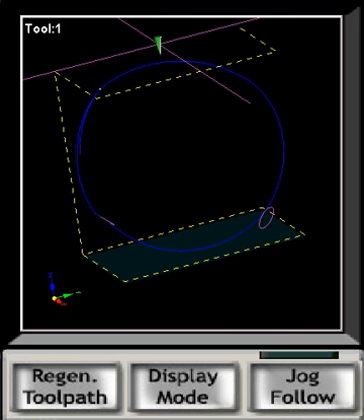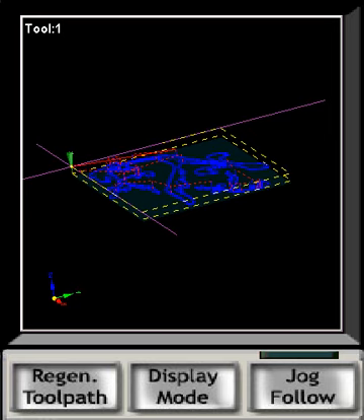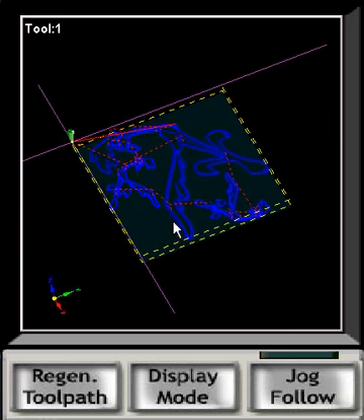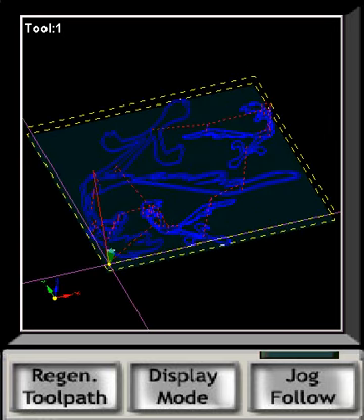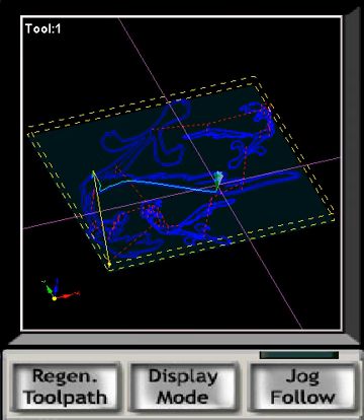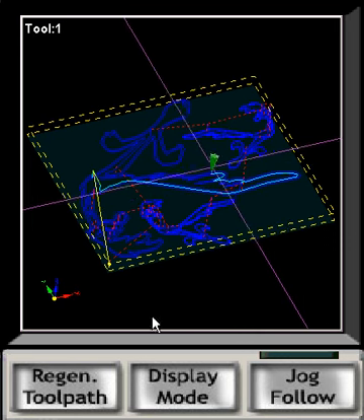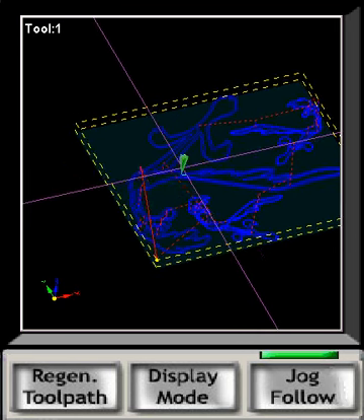And remember, it's important to zero your rotational axes if you're going to load another job. And we'll load the Roadrunner file again here. And the Roadrunner file loads up and is ready to go. Jog follow mode again. And drop off from jog follow.